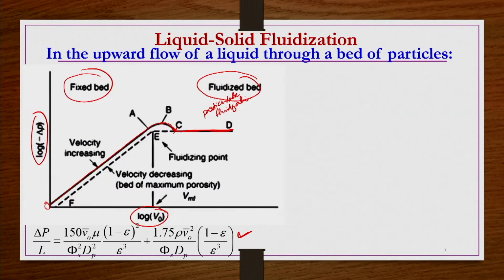Okay. Now, if you want to decrease the velocity, you have seen that you have gone up to the particulate fluidization conditions. Rather than further increasing the velocity, so that the particles go out of the bed and the fluidization goes into the pneumatic transport regime, let us not increase the velocity to such a high value, because the particles would go out of the column. We want to stay within the column, because we want to trace back the pressure drop versus velocity curve while decreasing the velocity.